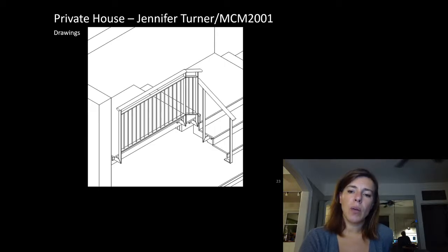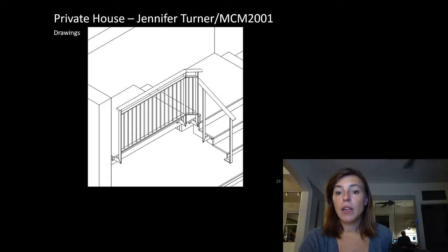So for this one, when I looked at it, the thing people always come to us and say is aluminum is lighter, therefore we want to build out of it because everything is going to be smaller and cheaper. Aluminum is less strong, and it's also way less stiff. It's about half as strong, but a third as stiff. And so things that might not be a deflection problem for a guard in steel can become a problem in an aluminum guard.